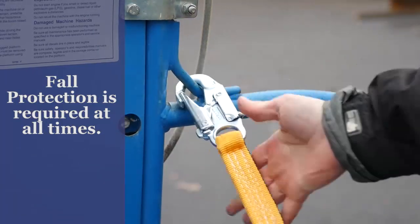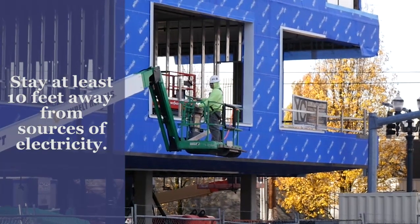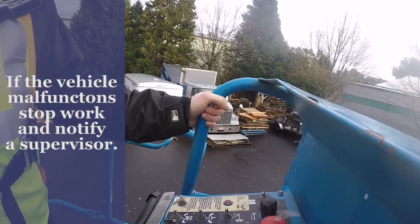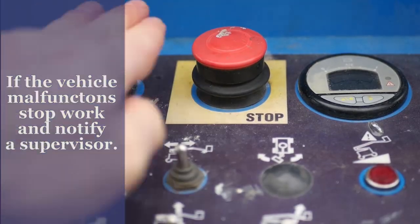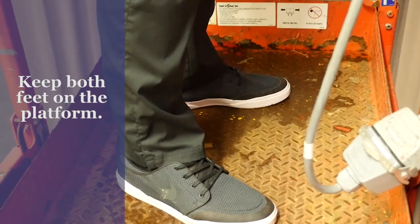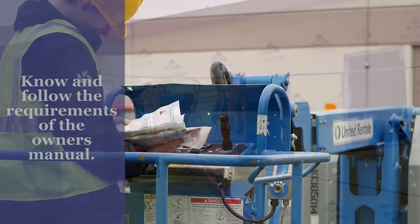Connect to an approved fall protection anchor point. Maintain a distance of at least 10 feet from electrical conductors. If the vehicle malfunctions, stop work and notify a supervisor. Keep both feet on the platform at all times. Know and follow the requirements of the owner's manual.